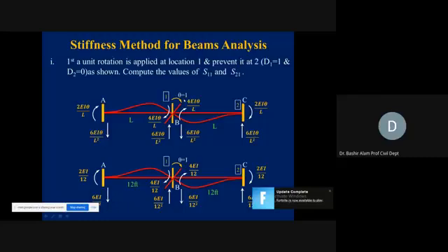Now it will cause unbalanced moment now in that particular span. So we need to balance that by a balancing couple. So that is how these vertical reactions are generated at the ends now. 6EI theta divided by L square, 6EI theta divided by L square. Similarly, for the BC span, you can use the same concept and you can develop these member actions. Now, this was the general case now at 1.